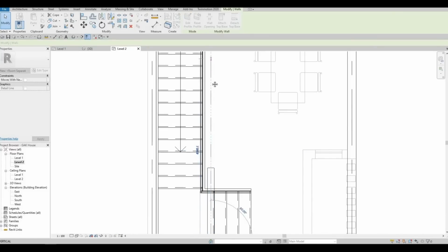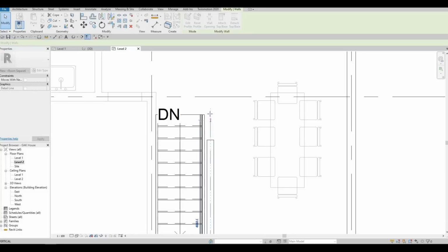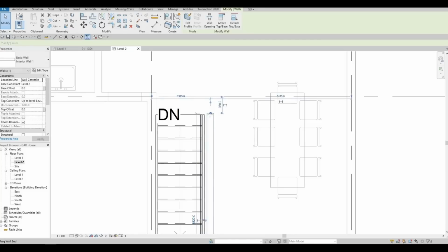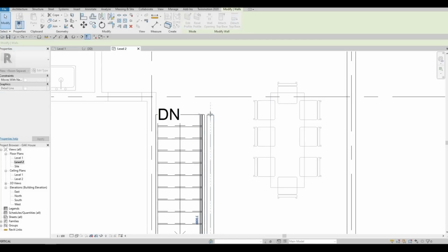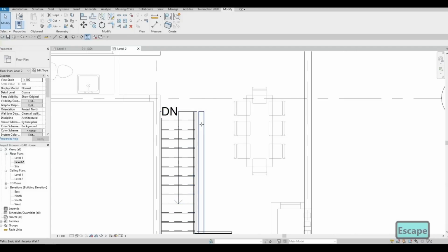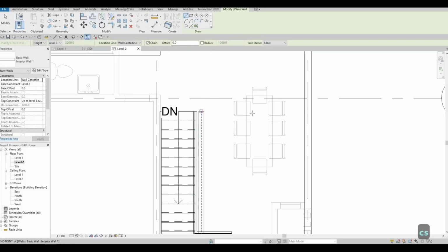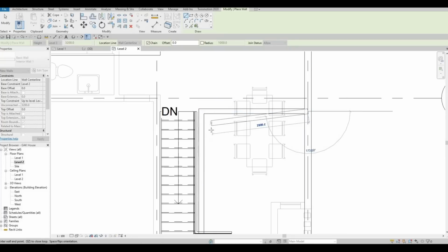Now I could just move it like that using my mouse, and all the way to this. And then now that we have our interior wall, you can type in CS, and then you could easily add walls now. So what I'm gonna do is add a wall like that, and we could just move it later on.